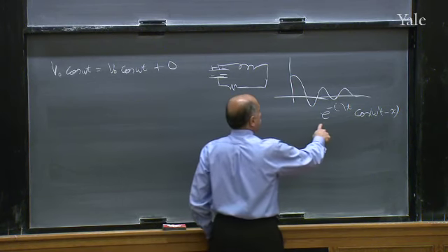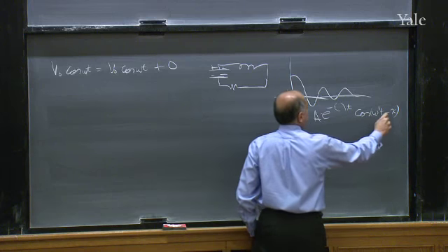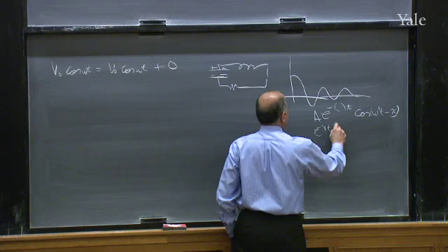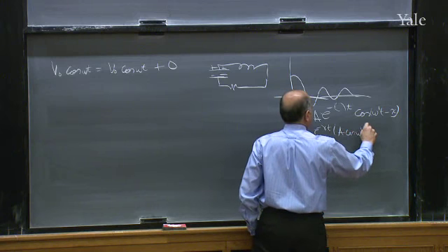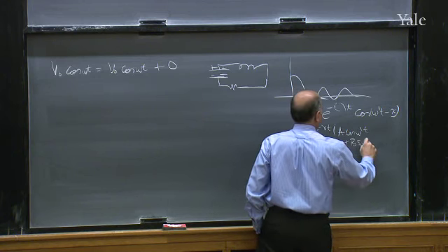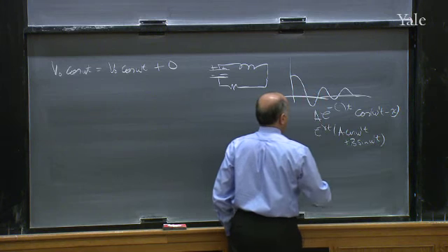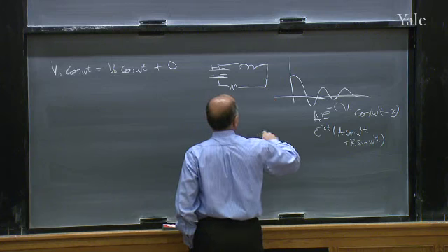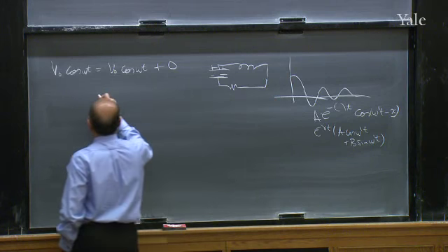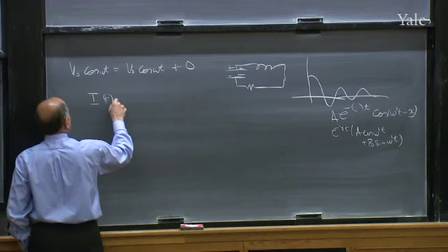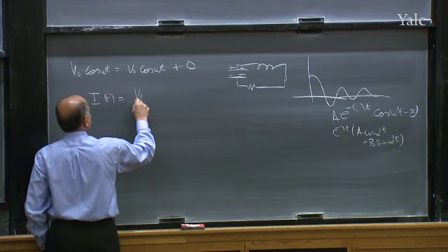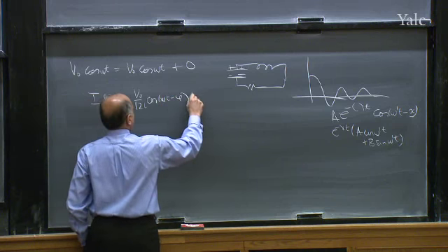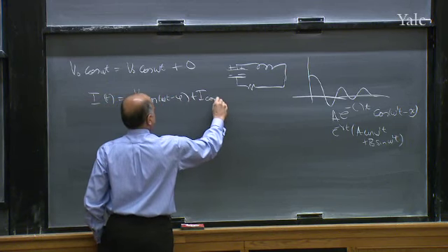And this thing had two free parameters. There's an a here and a chi here. Or you can write it as e to the minus gamma t times a cosine omega prime t plus b sine omega prime t. No matter how you write it, this solution to 0 external voltage is called the complementary solution. And the final solution for I is really what I wrote, V over mod Z cos omega t minus phi, plus this complementary function.